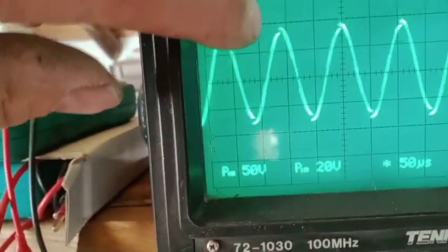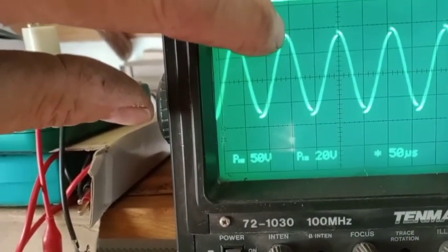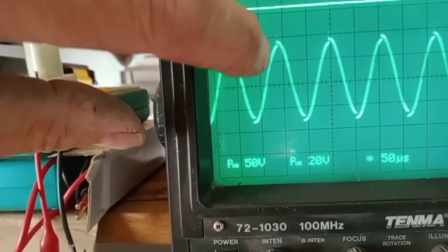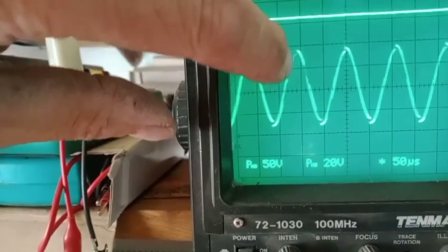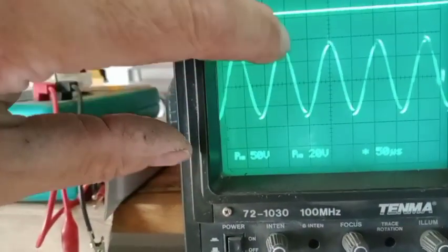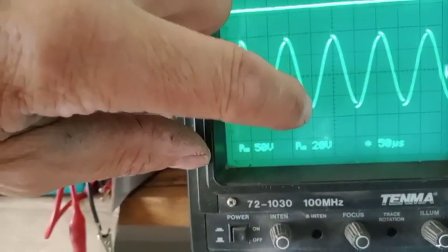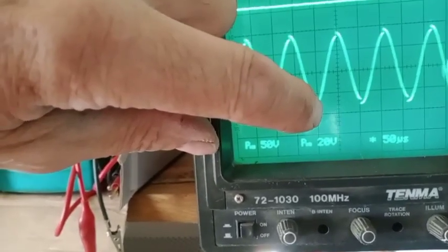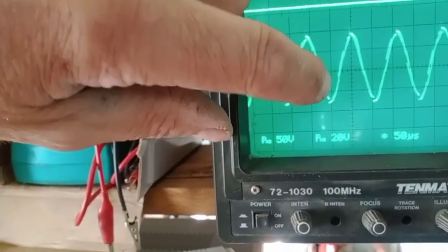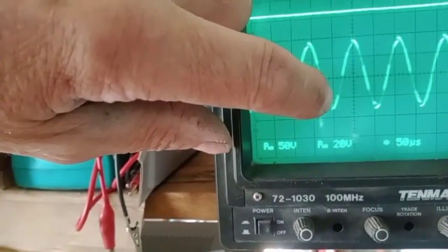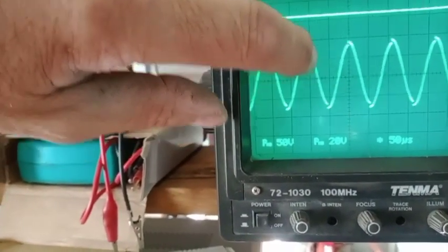You can see here that at the peak of the sine is the switching at resonance, at LC resonance. And this is where the polarity of the square signal changes. So I can only use this side of the falling sine, and in the negative part, it was noted that the pulses are counterproductive. The feedback is negative, not positive. So it should be reduced to 1/4 of a cycle in this setup.